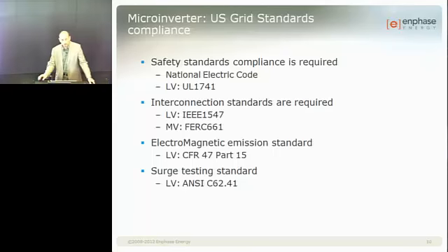Our standard unit works either in 240 split phase or 208. In 208, that means that we will connect a unit to two of the three phases. So we only do single phase systems, either connected line to line in a split phase installation 180 degrees apart, or 208, 120 volt line to neutral, 120 degrees apart. So we have single phase inverters at this point.